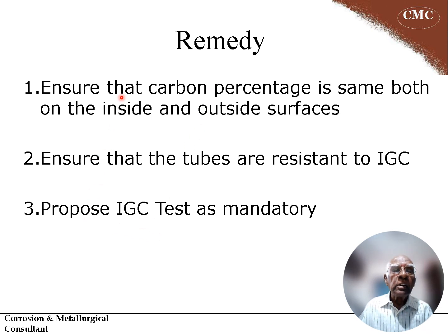So, in order to ensure that this should not happen in the future, propose IGC test as a mandatory test for accepting the tubes. It's a kind of quality control step. So the case is related to a metallurgical defect leading to corrosion of a